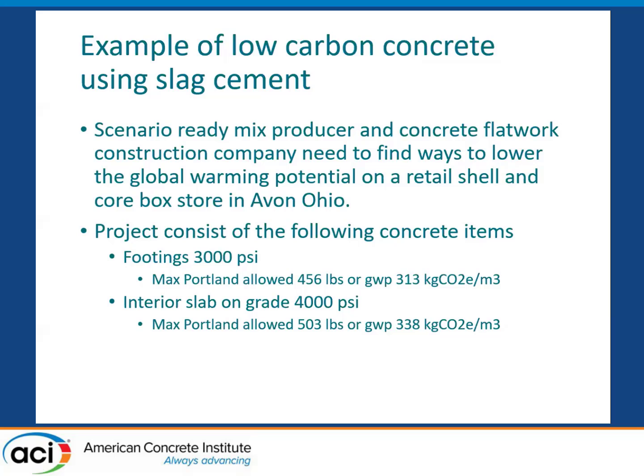So in this case, this could be restricting the product and the way that the contractor could be able to do it. He might be all right with that 3,000 footer, but he could have some issues when he's trying to do the finishability on that 4,000 interior slab on grade. So as we can see with these numbers, we've got to watch how we're doing it.